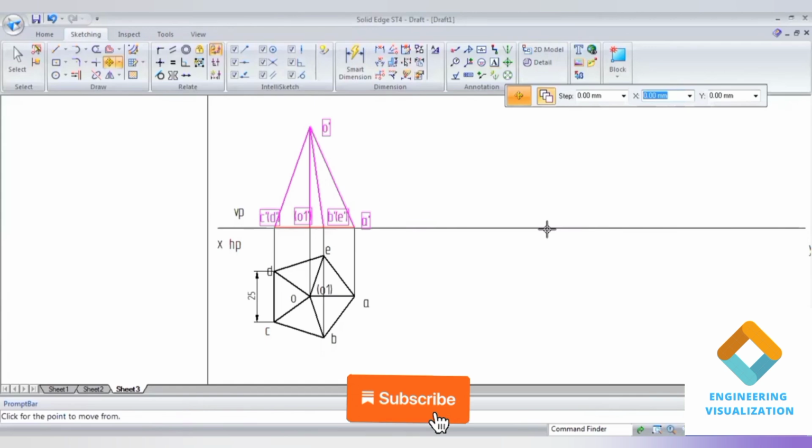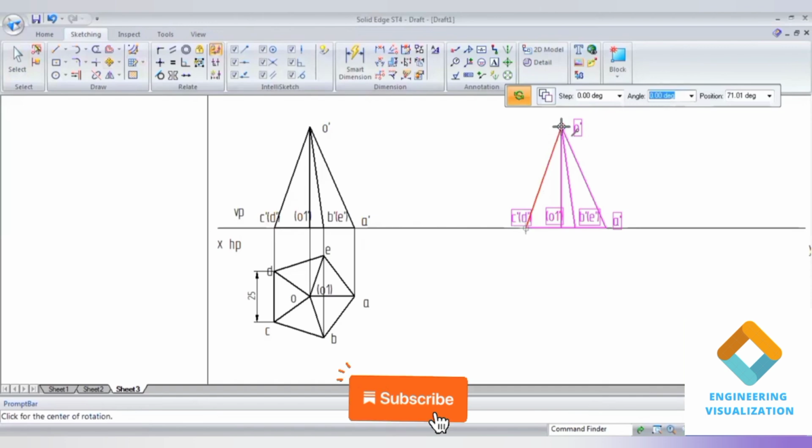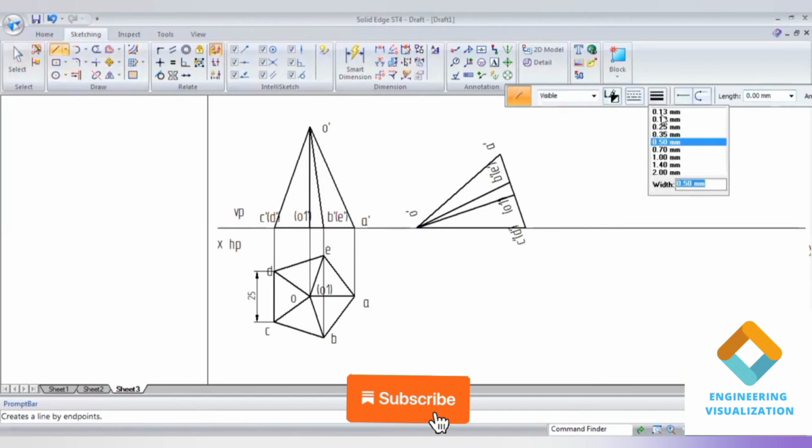Copy this, use the move command, slide along the XY line and then select these heads. However it is in the solution book, I'm following the same procedure here. Now project downward to complete the second position top view.